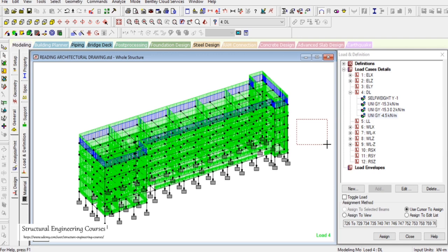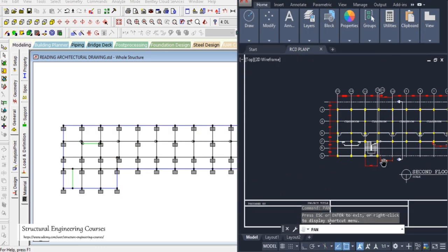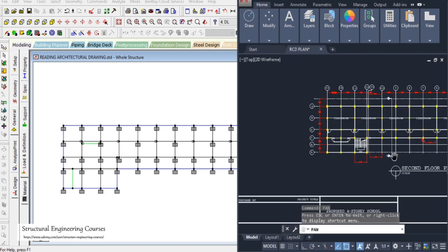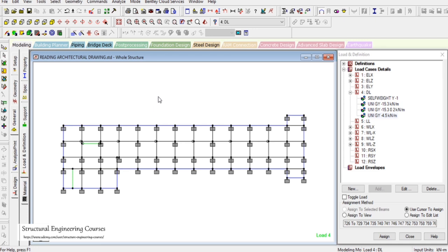So with this approach, we have calculated all the dead loads except for the staircase loadings. Here we can see that staircase dead loading needs to be considered, and the dead load due to slab also needs to be considered. Considering the spans are very short, in the range of 3.5 to 4.5 meters only, we can take a 150 mm slab comfortably for this type of arrangement. The slab is also two-way here, and this span is also a two-way span.